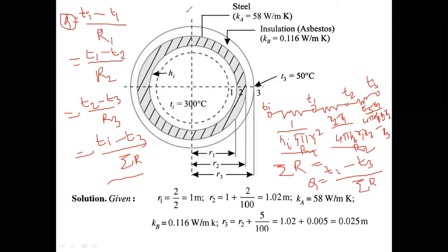Okay, all of you understand? Any doubt? So for any problem of heat transfer, the basic important part is that first you try to draw the schematic diagram of the figure, then try to draw the thermal circuit like an electrical circuit, and from this find out what is the total resistance.